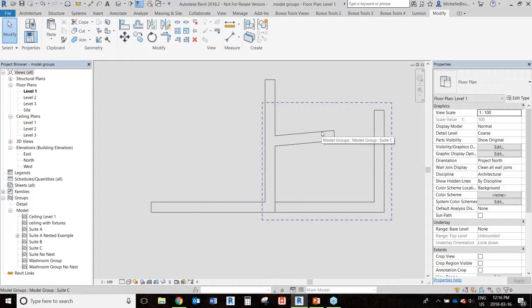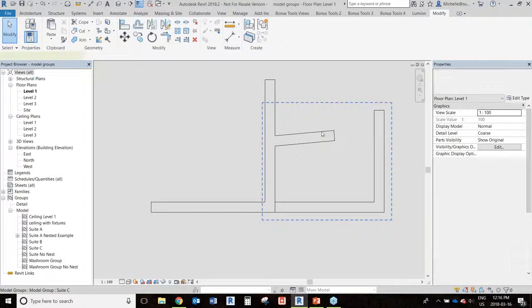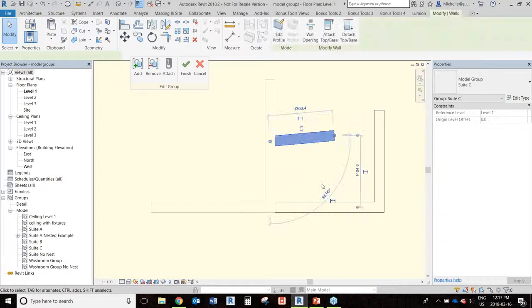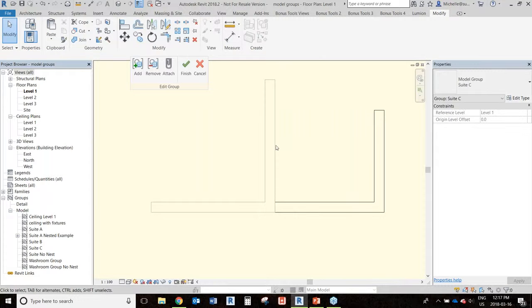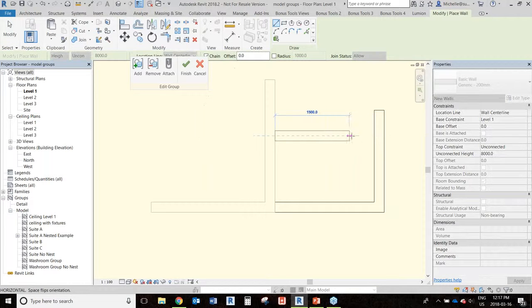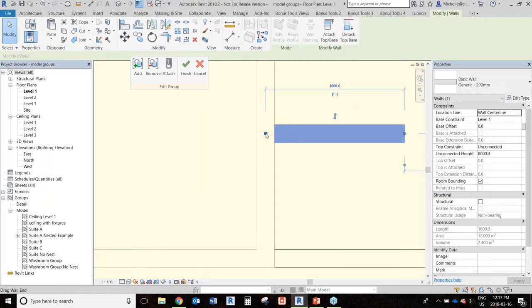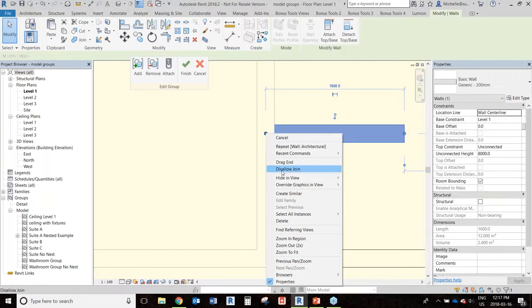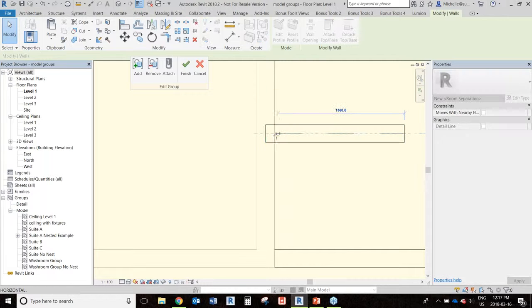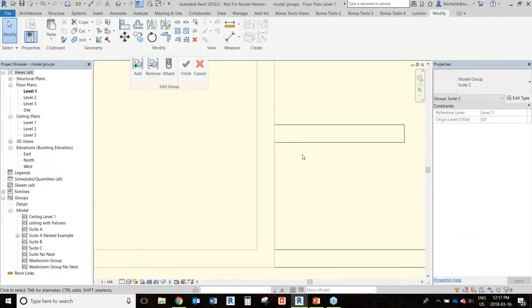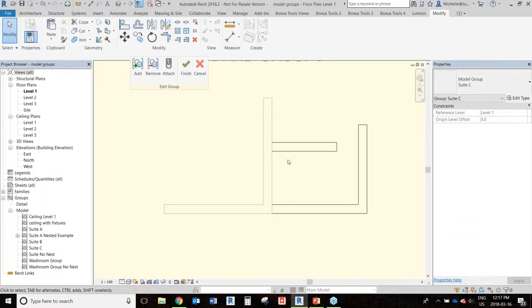So it's always best to assume that it won't be, and then you don't have to worry about it if it does happen. So for a lot of these walls, you have a couple options. You can allow the join here and then just right click on this button to say disallow. And then you move it to butt up to that other wall.